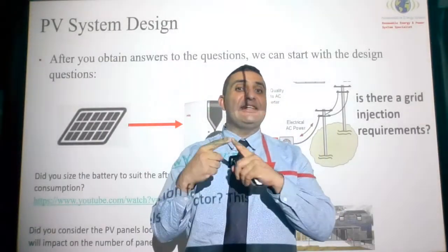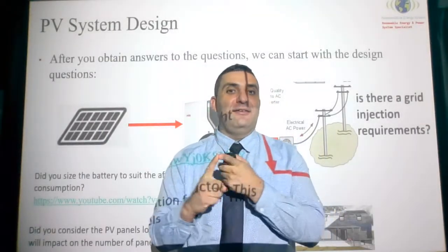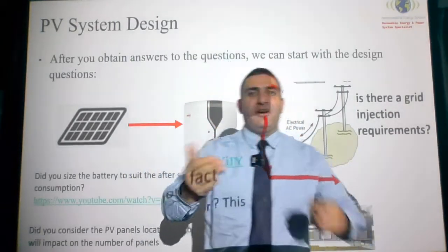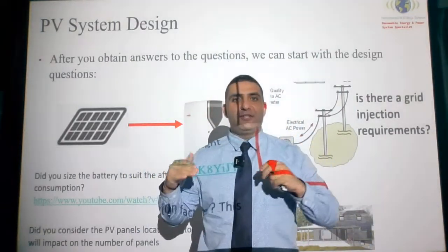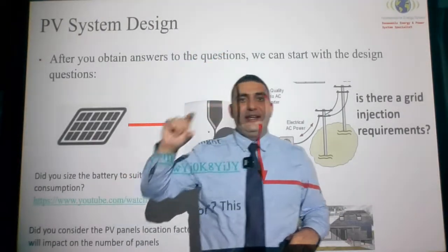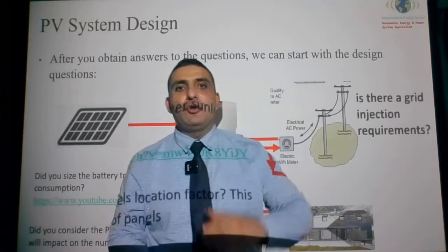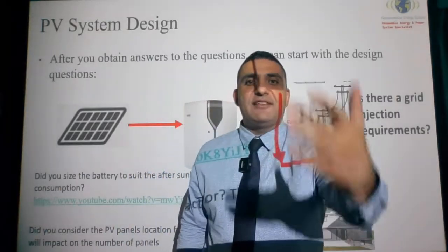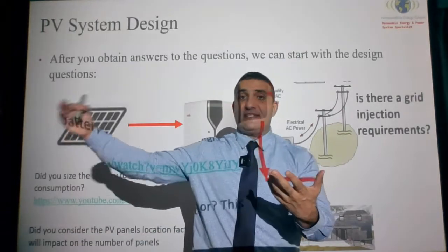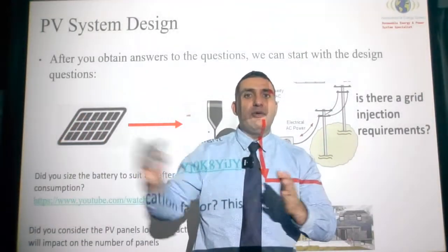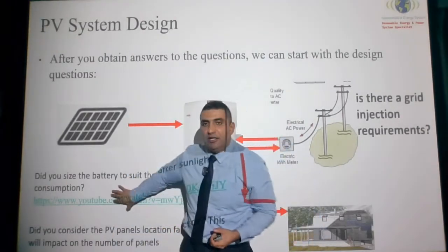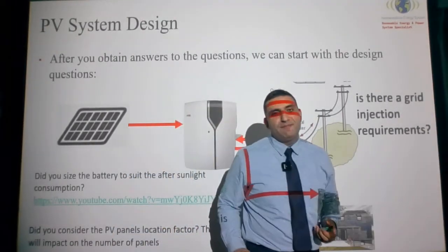the battery doesn't only work during dark time. We know from previous YouTube videos that the solar power goes up and down. Maybe your battery, depending on your PM load, will start working at 3 p.m. or 4 p.m., even though the sun goes down at 7 p.m. So for these 3 hours, you are consuming energy from your batteries. That's why you need to take it into consideration.